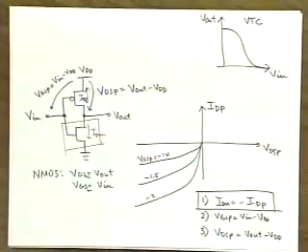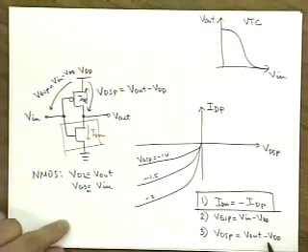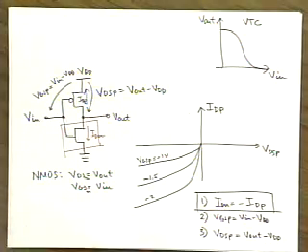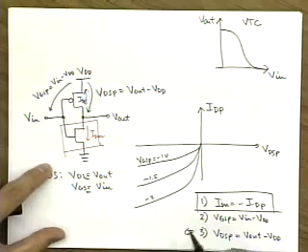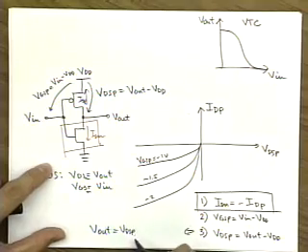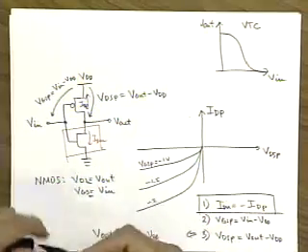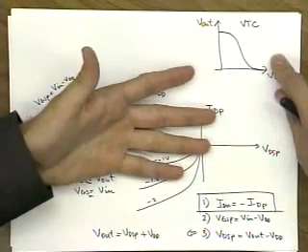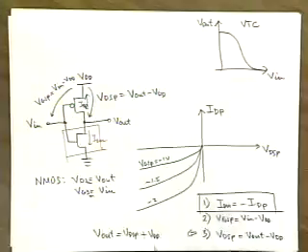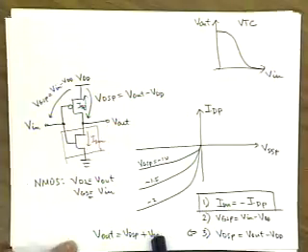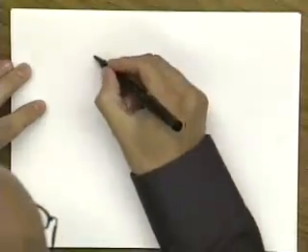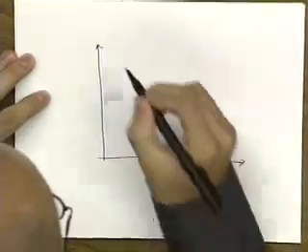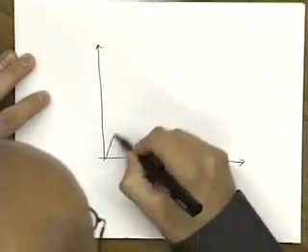And then we have this VDSP is equal to V out minus VDD. So what you need to have in terms of V out is VDSP plus VDD. So what you need to do is basically first flip this curve to change the sign, and then shift it over by VDD using this relationship. And then what you end up with is load lines for NMOS.